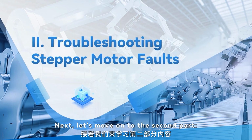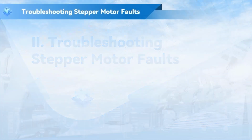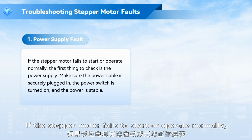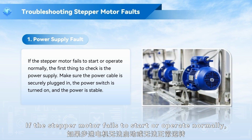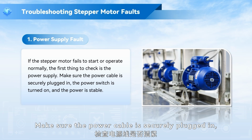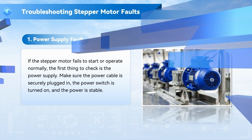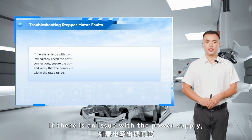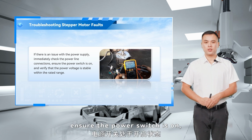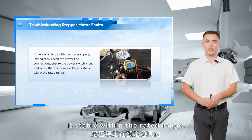Next, let's move on to the second part, troubleshooting stepper motor faults. 1. Power supply fault. If the stepper motor fails to start or operate normally, the first thing to check is the power supply. Make sure the power cable is securely plugged in, the power switch is turned on, and the power is stable. If there is an issue with the power supply, immediately check the power line connections. Ensure the power switch is on, and verify that the power voltage is stable within the rated range.